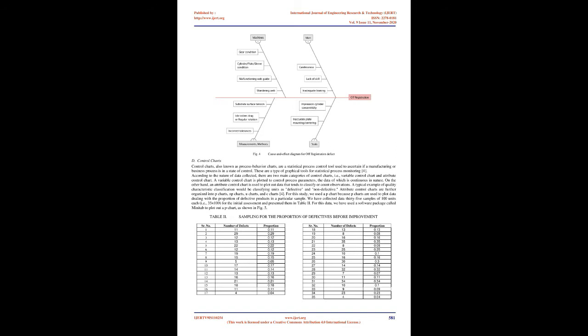A Pareto chart was designed based on data obtained in Table I, identifying the most common types of defects. Figure 1 shows that there are 3 most frequently occurring types of defects. These are breakage, blisters, and off-registration, which account for about 41%, 26%, and 15% of the total defects each, respectively. These 3 major types of defects sum up to 81.98% of the defects overall. Hence, for this study's scope, the causes of the mentioned types of defects will be investigated.